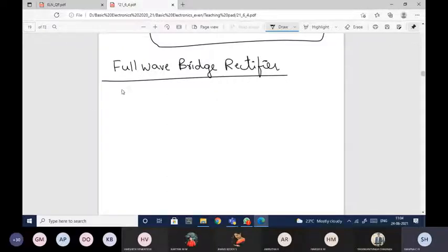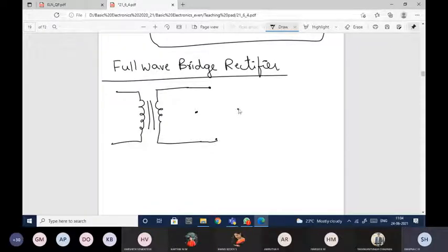Okay, so for the circuit here, I will not use any center tapping, to overcome the disadvantage I have with respect to the center tap. That is what I'm trying to eliminate here. So you need to remember the diagram. For the others it was simple, but here we'll be using 4 diodes. That is the drawback. Here I'll have the resistance RL and I'll be using 4 diodes.